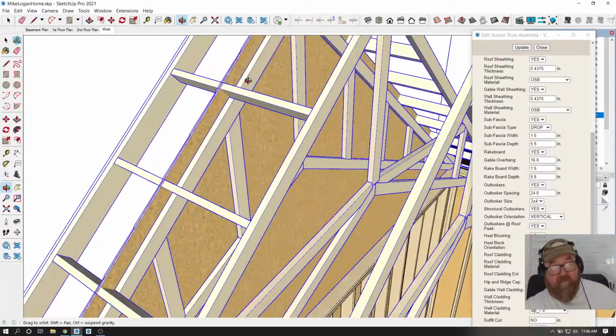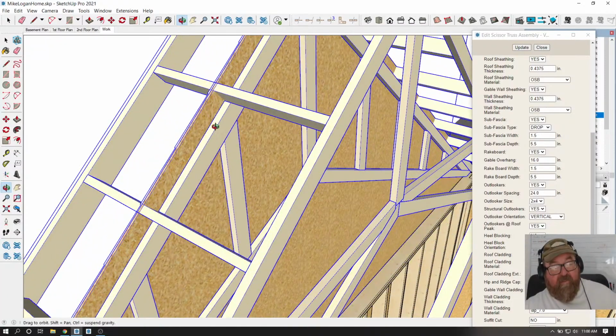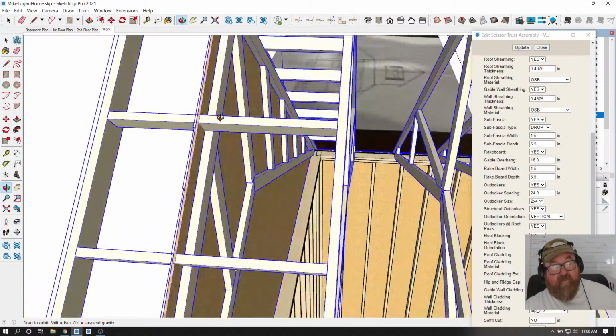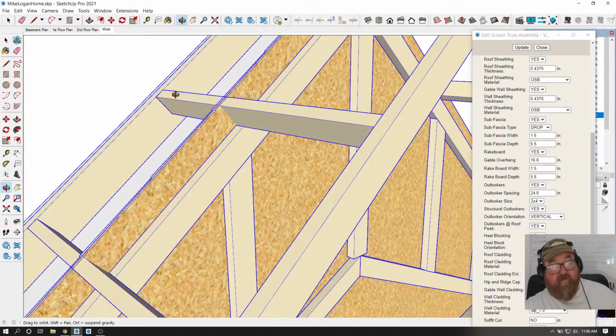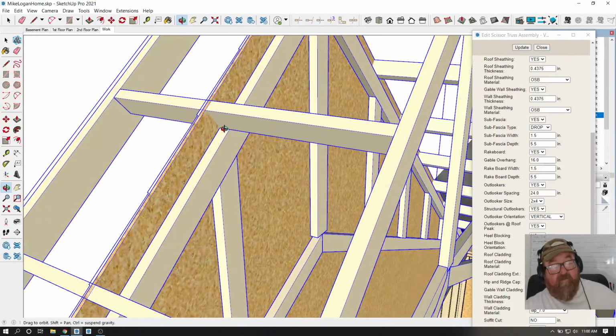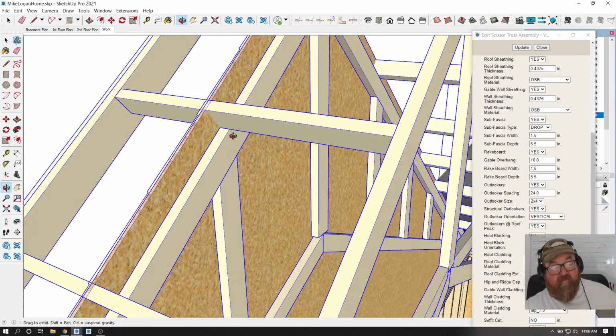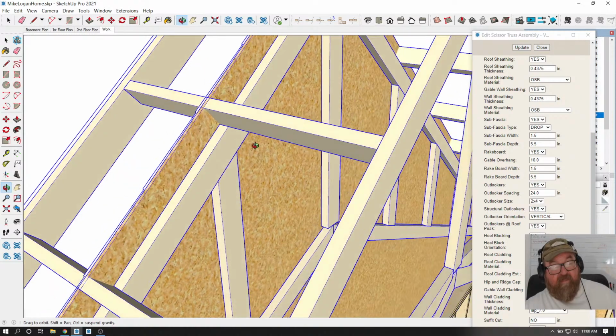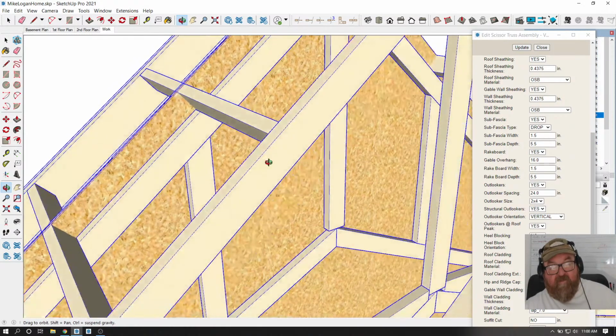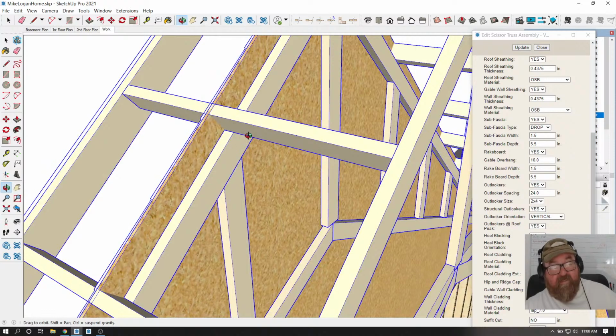But what you can do is ask your roof truss company to drop the gable end truss and run these outlooks over the top of it, and they're cantilevering out, and they're super strong this way. If this truss comes up to here, then you either have to notch the outlookers out, and that's why they lay them flat sometimes. But that's when people order trusses and they don't think about it, that's what they get stuck with. If you'll plan ahead and do this properly, you'll run into this in your model or